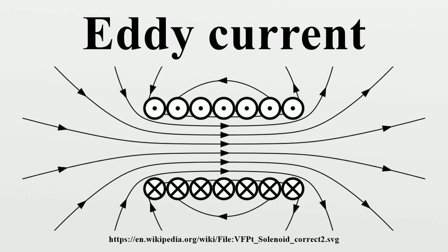Side effects. Eddy currents are the root cause of the skin effect in conductors carrying AC current. Similarly, in magnetic materials of finite conductivity, eddy currents cause the confinement of the majority of the magnetic field to only a couple skin depths of the surface of the material. This effect limits the flux linkage in inductors and transformers having magnetic cores.